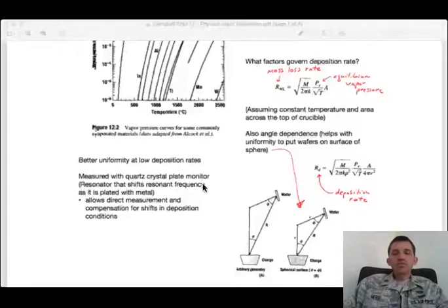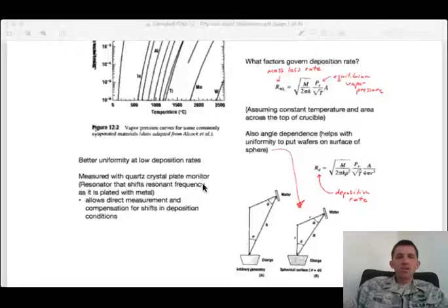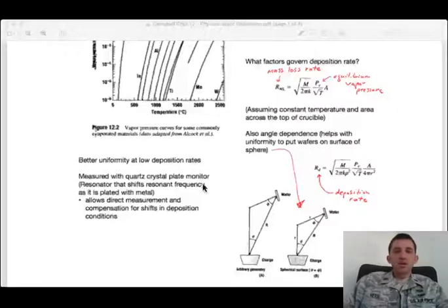And so evaporation is fairly simple, which is a good thing, but you don't always get very good coverage. And this is due to the fact that those metal atoms are just spraying out in all directions, and they just go where they go and they stick where they stick, and that forms your metal film.